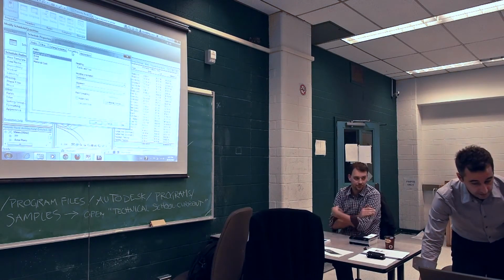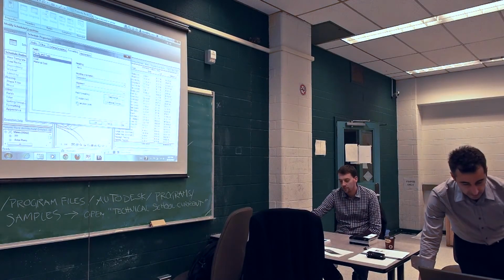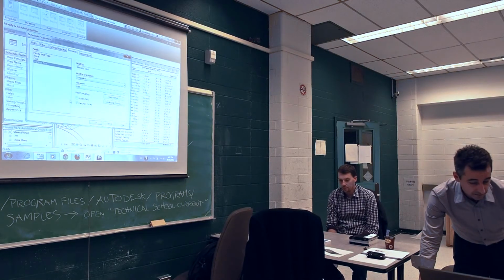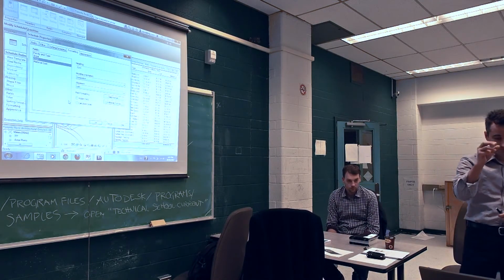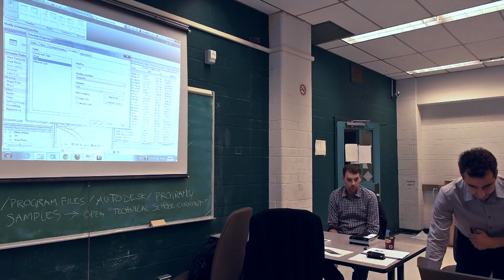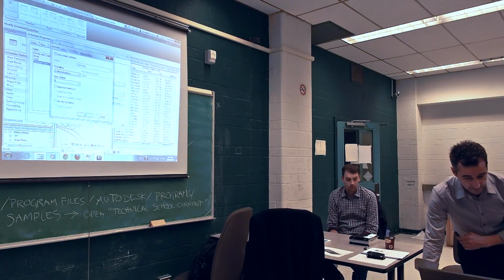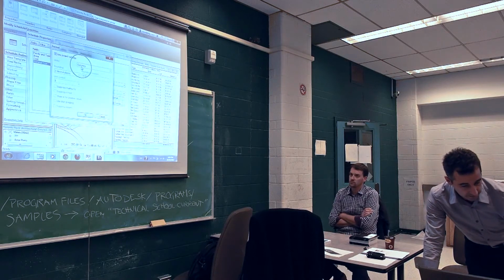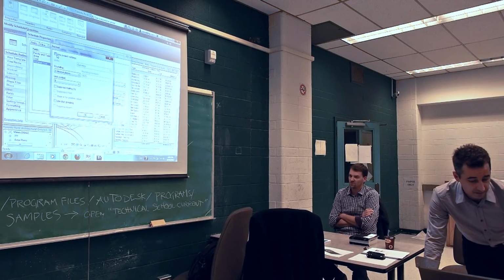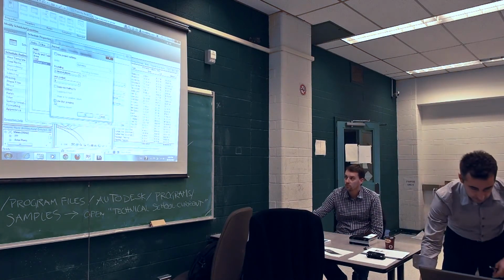Next tab, formatting. I have a little bit of control on the formatting, and the most interesting thing is area in here, because I need to calculate the total area and the total material cost. I need the total cost. The cost is not going to need the total because that one applies per unit, per square foot, per cubic foot or cubic meter or whatever the unit is. Also, for the cost, I would like it to show with 2 decimal places and with a $ sign. By default, this is checked, and it's up to the project settings, although this is currency. But if I want to refine that, I'll uncheck. This is kind of an override for the project settings, and then I can choose different options in here. And if I actually need to use digit grouping to define thousands with a comma, then I can enable this one.